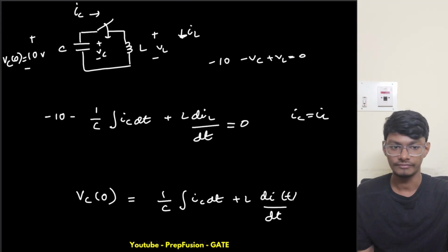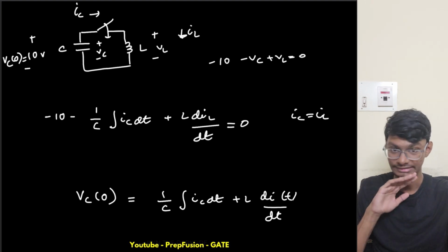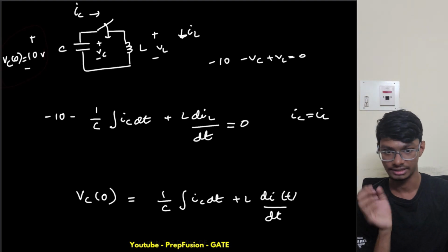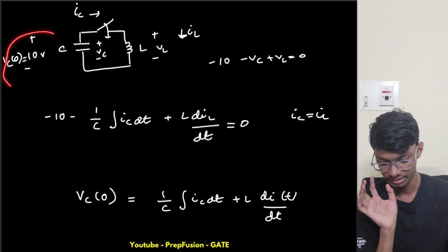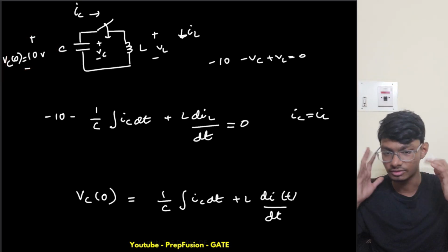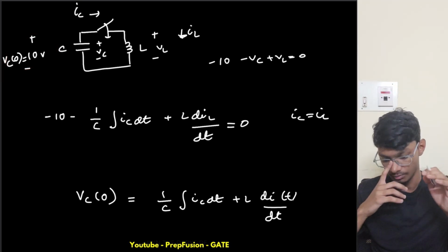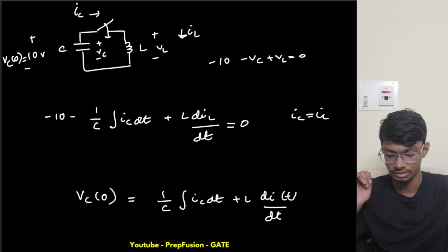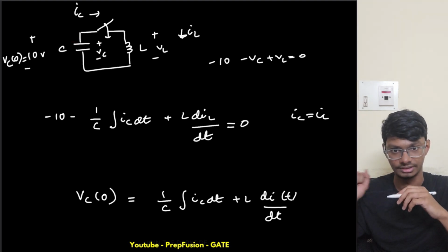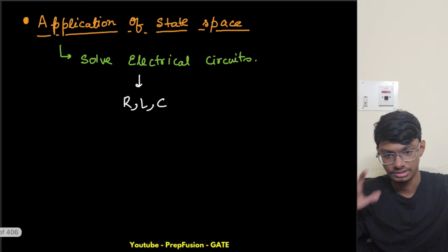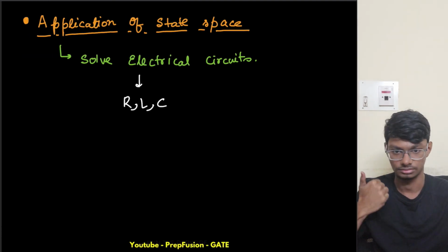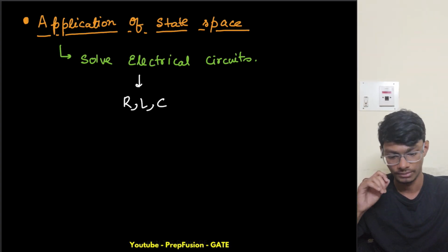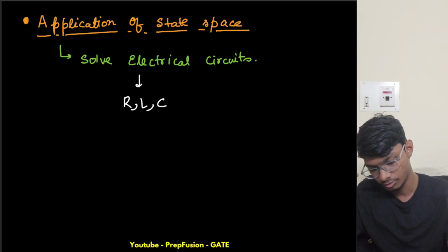If you couldn't understand this, it's not that important as such. It's just to understand that if my circuit has some initial voltage, we don't think of this that much because we solve it anyway, but the main thing is we apply the principle of superposition. We assume the capacitor to be 0 volts, and then some 10 volts is beside it. That is what we basically do. So this was one thing to keep in mind. What was the main point I was getting at here is that